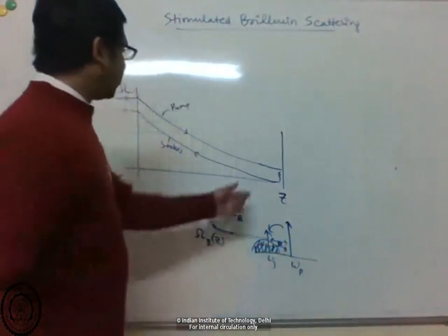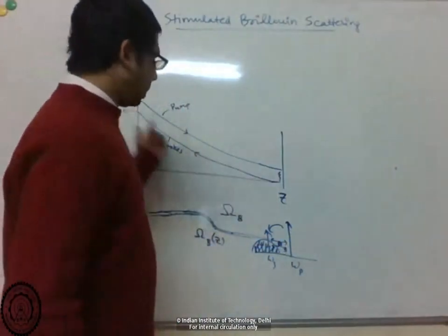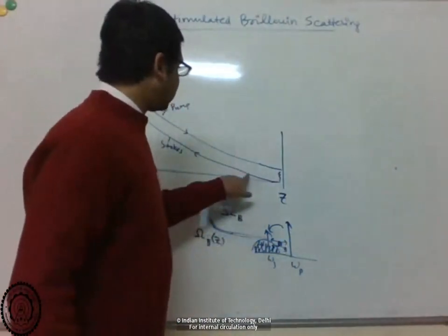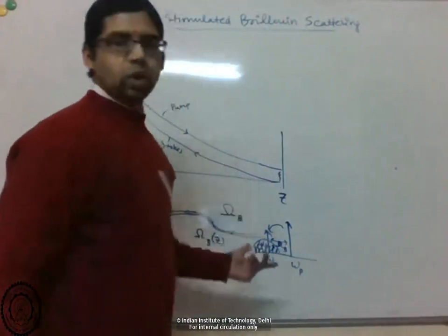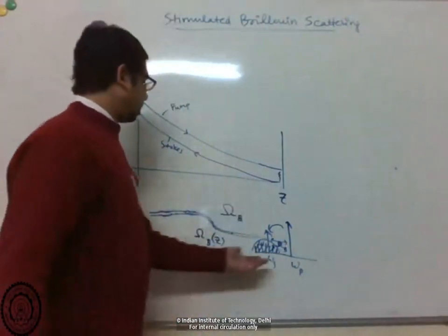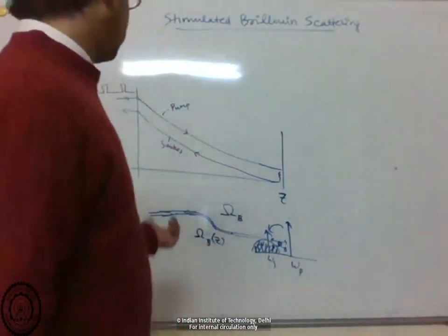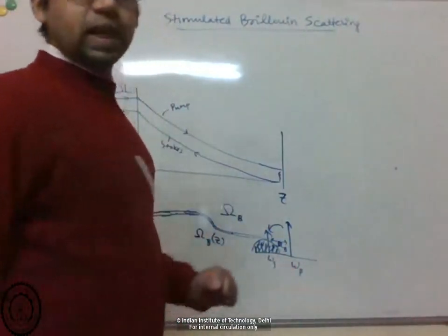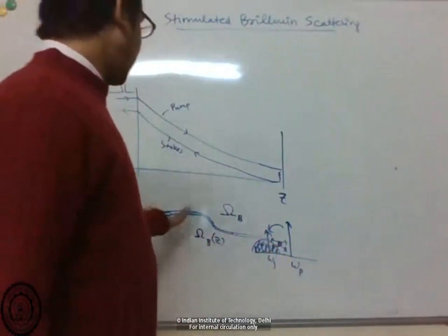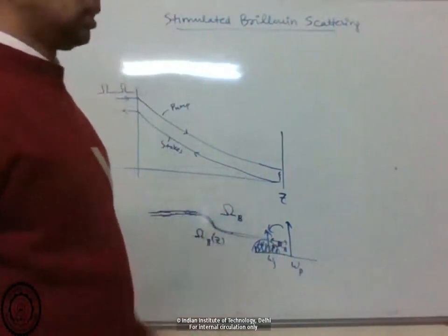So the wave doesn't add up, because at different stages you are adding different frequencies which are not coherent with each other. So inhomogeneities in the fiber cause this SBS scattering to be inefficient, and that helped.